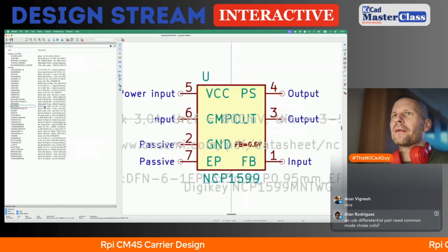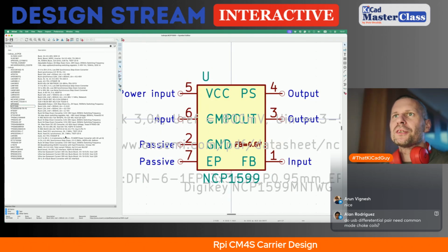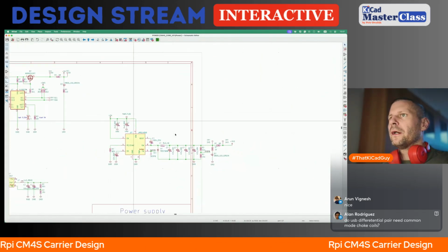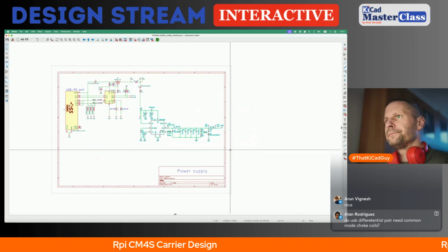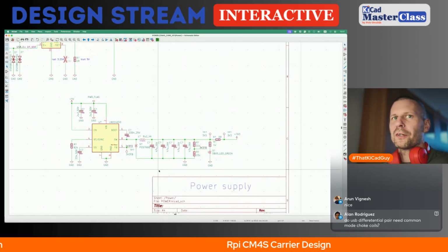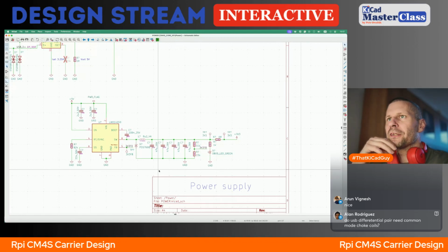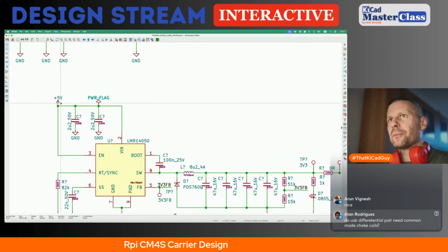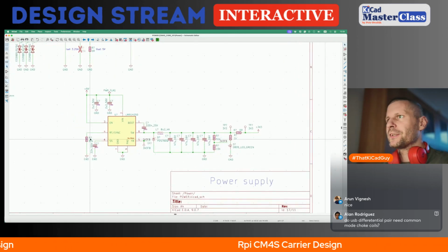Yeah, I can use something like this. This is 3 amp output, but if we change the output voltage, it won't work. And this one will work. I will keep it. To have the buck converter able to work reliably with some reasonable headroom for current is always a good thing. That's not a bad design behavior to keep reasonable headrooms. We can change this, the frequency.